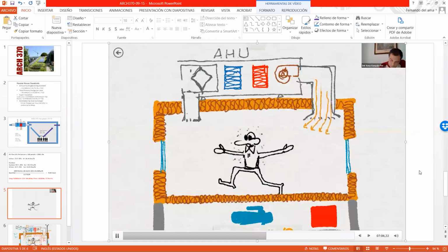Then this air will go through the people, so people will breathe this air, but at the same time, they are filling that air with moisture, particles, pollutants, and now we are going to recirculate this air through this grill to the heat recovery device. So it goes through the heat recovery. Okay, so this is the air supply, and the other one is the air return.